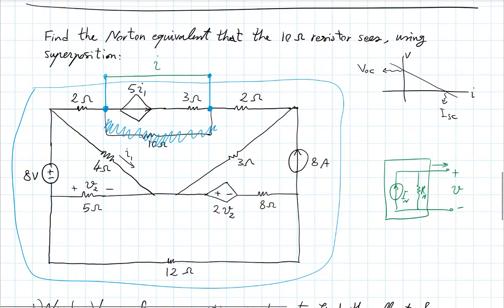So you see, this is a matter of being consistent with the way we have defined our things up there, because you can see here that if that current I increases in the circuit, so if you connect something here that takes some of the current outside the box, then you have less current going through the RN resistor, and so the voltage between those 2 points actually drops, right? So the way I have defined my IV characteristics is consistent with such a direction, the definition of directions being like this for V and I.